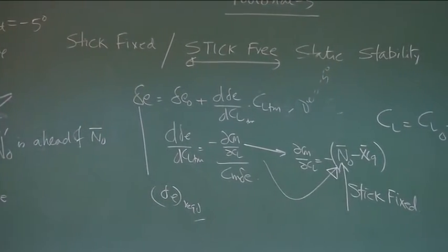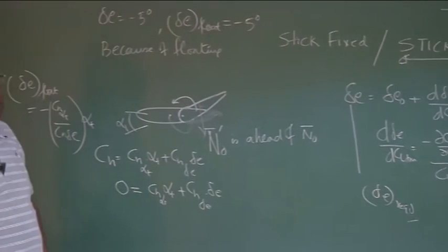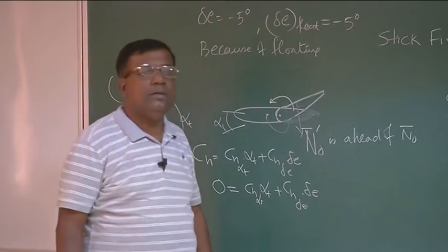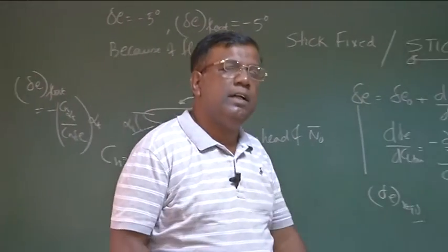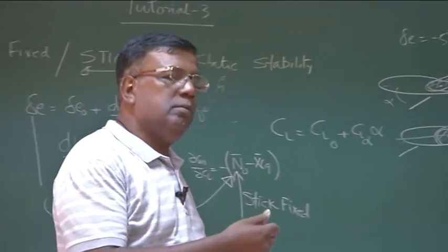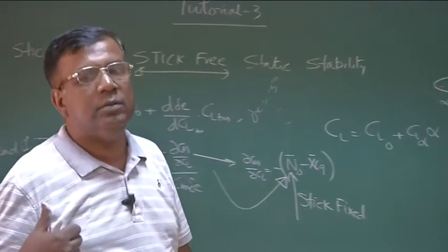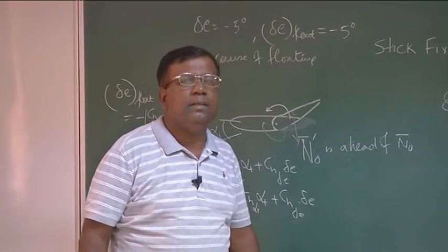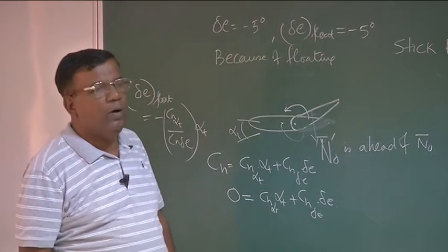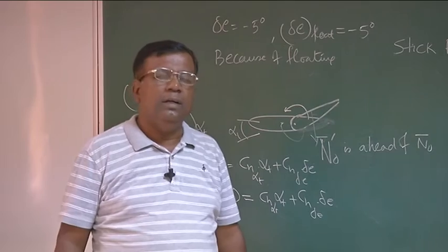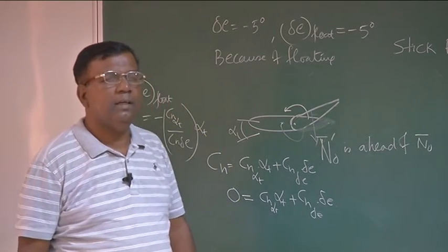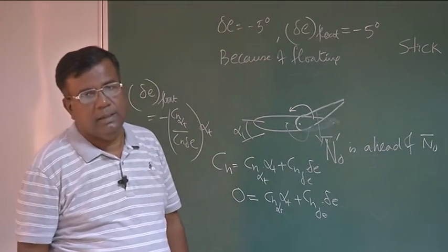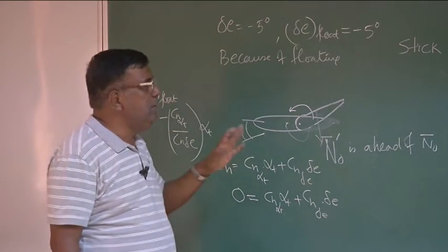And also, we know stick-free case is valid or really realistic when you are talking about reversible control. That is, if I move the elevator, the stick also moves. If I move the stick, elevator also moves, right? But for modern aircraft, that reversibility is not there. It is now irreversible. So for that, the stick free concept loses its significance as far as finding the stick force is concerned, right? So this should be very, very clear.